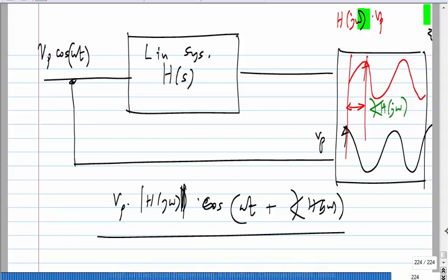So this way the analysis of linear systems is very easy. What makes it easy is linearity and superposition, right? You can take any complex signal and break it down into some set of convenient signals. One convenient set of signals is the set of sinusoids. They are orthogonal basis functions for representing signals, but you could do it in some other ways also. Because superposition is valid, you analyze the linear system for each of these constituent signals separately and then add them up in the right proportion.